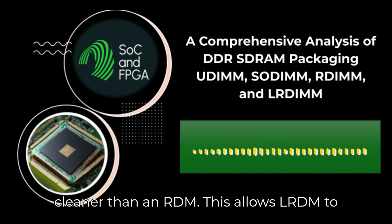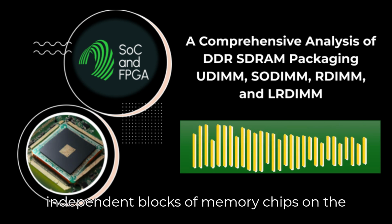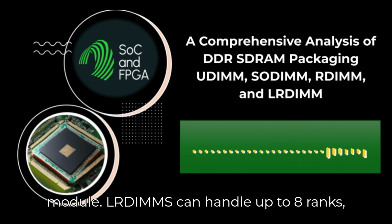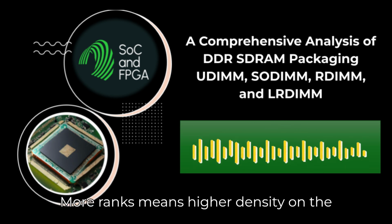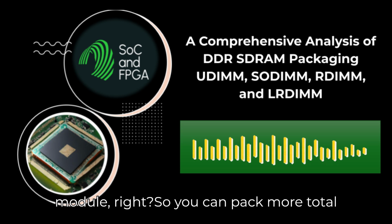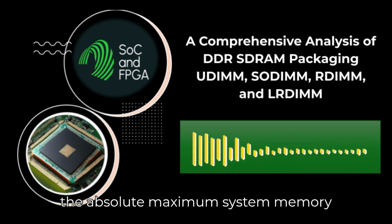This allows LRDIMMs to support more ranks. Think of ranks as independent blocks of memory chips on the module. LRDIMMs can handle up to 8 ranks, whereas RDIMMs typically top out at 4. More ranks means higher density on the module, right? So you can pack more total memory into the same number of slots. Precisely. That's why LRDIMMs enable the absolute maximum system memory capacity.